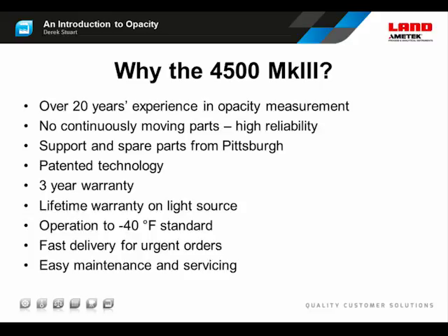And what we've found in the US is even though the 4500 Mark III will measure mass emissions of particulate matter, and we do sell it for that purpose in Europe, US customers are generally reluctant to use an opacity monitor to measure PM. So the suitability of a 4500 for a specific application does depend on the rule, and especially for incineration, that's worth checking.